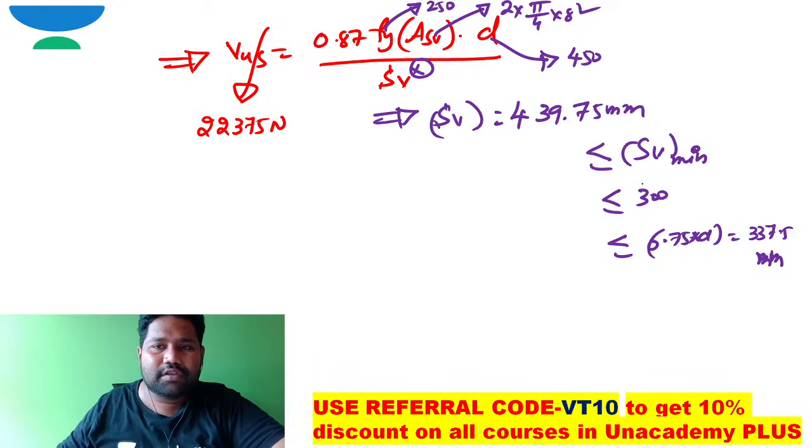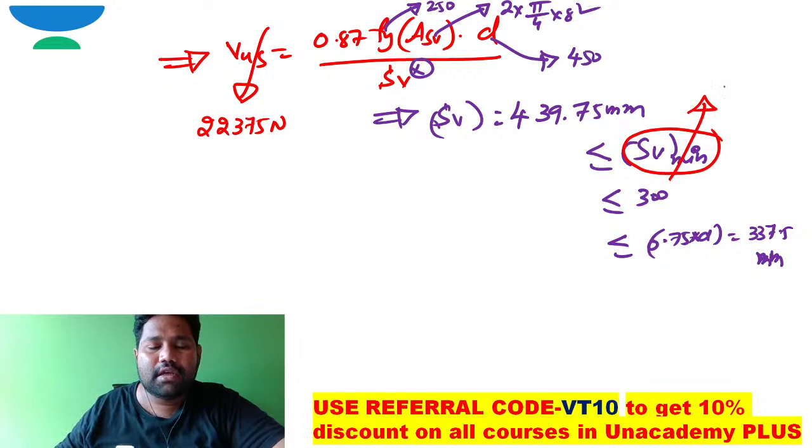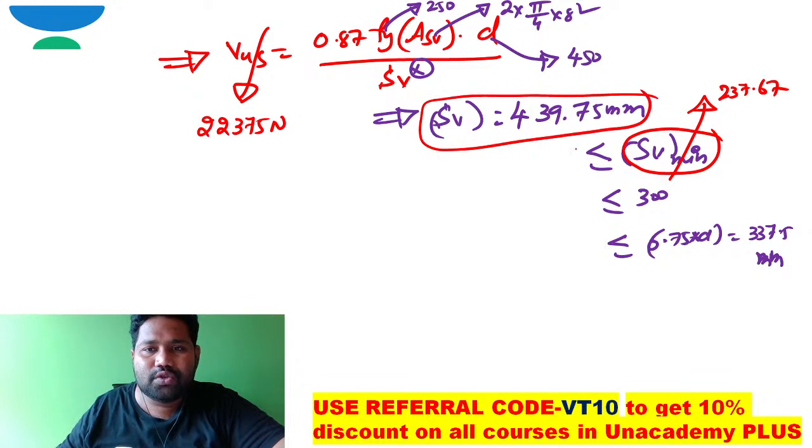And in your previous question, what is this Sv minimum? What is the minimum shear reinforcement spacing that you got in your previous question? The minimum shear reinforcement spacing is 237.67. Even though you got the spacing from the equation as this much, this value should be less than this one, no?